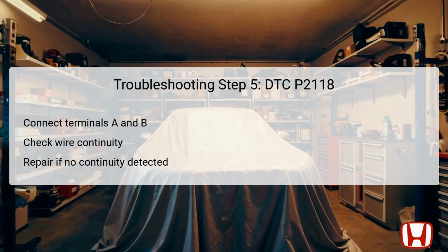Should this check reveal no continuity, it signifies that there could be an open circuit within either wire, necessitating repairs between the throttle body and the PCM.